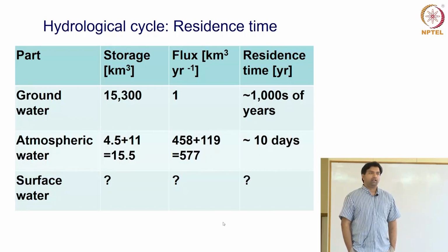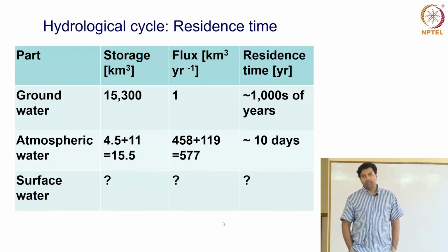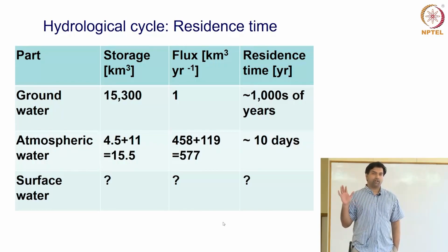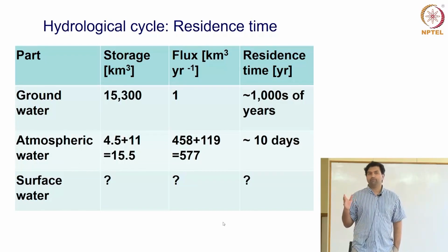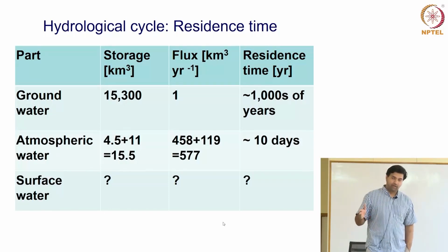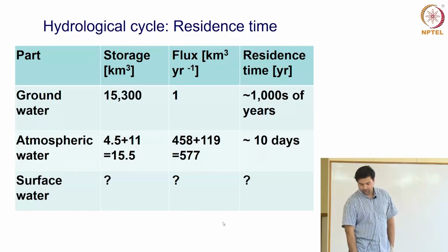That's typical. If you look at groundwater velocities, if you don't have any severe pumping and man-made artifacts, naturally water flows fairly gently because there's a lot of resistance. You have to move through the soil, through the porous media, and gradients are fairly small, not very steep. So water moves at about a few meters per year, a few tens of meters per year. So considering the global scale, on an average it takes thousands of years for water to move through the groundwater system.